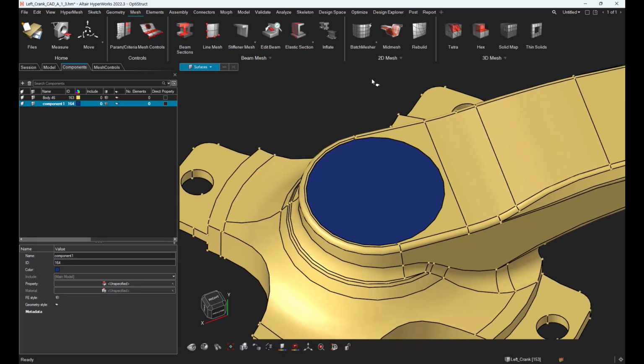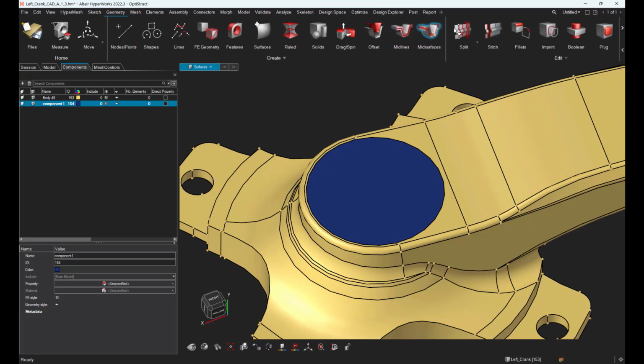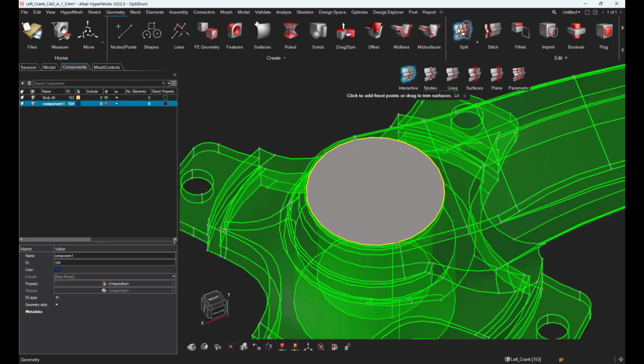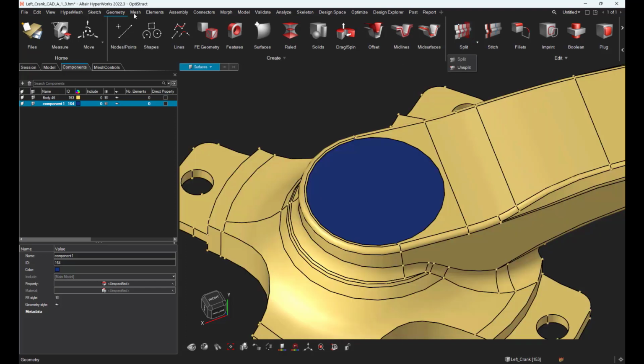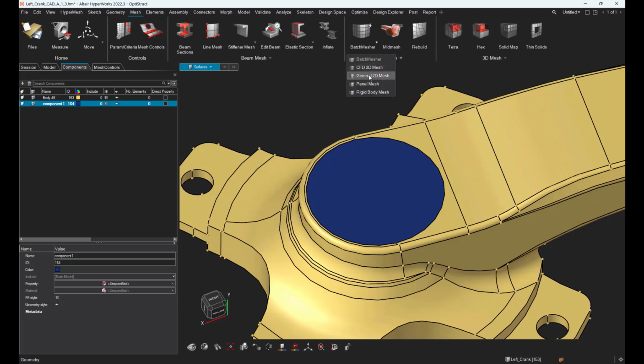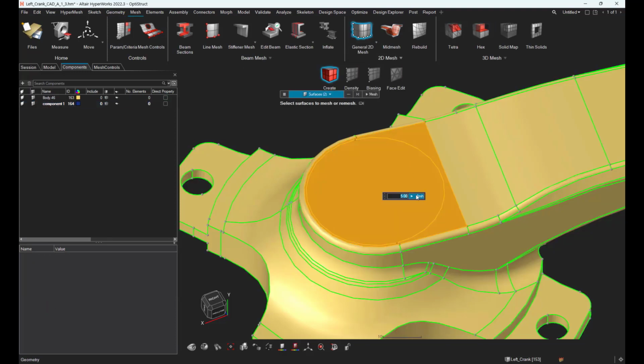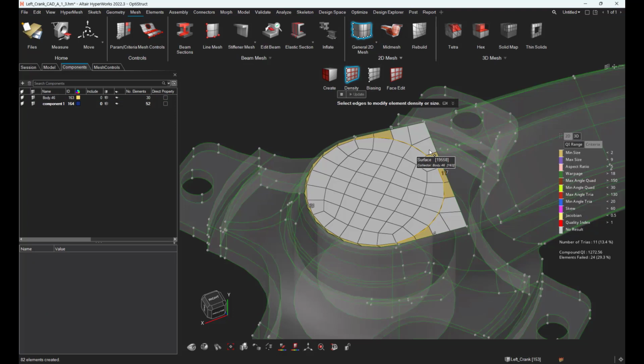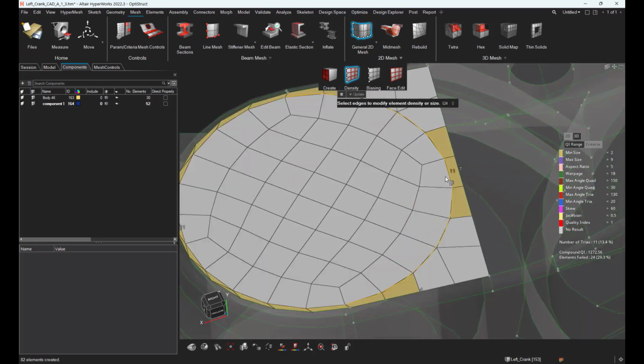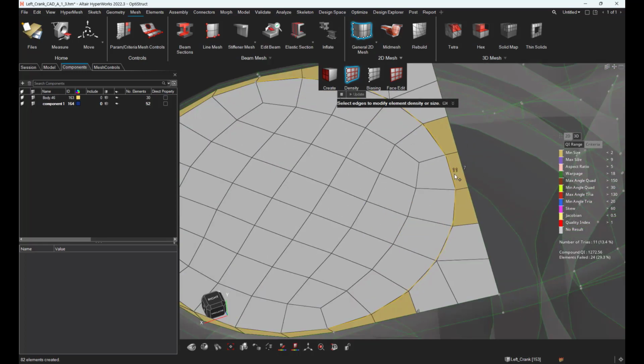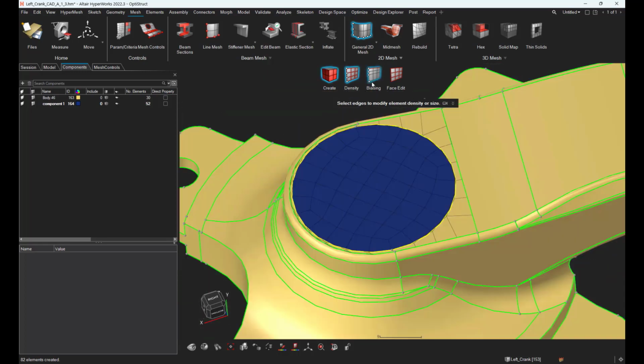So inside HyperMesh, you have 2 components correctly connected to each other in terms of the topology. Okay? If you mesh it with a general 2D approach, as you have a correct connected topology between the 2 components, you can have a perfectly connected mesh on those 2 components.